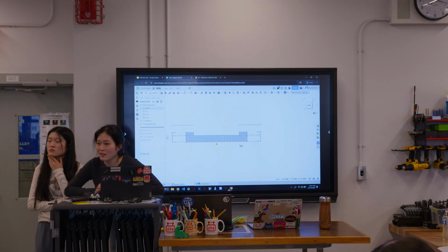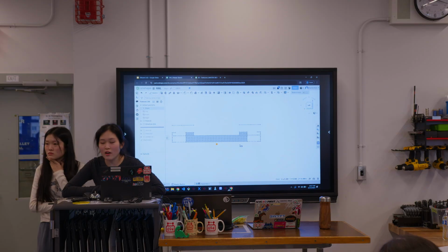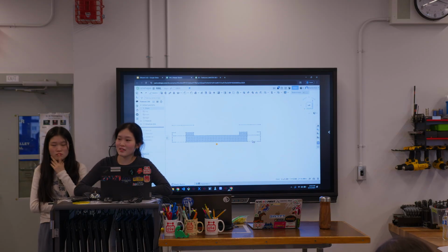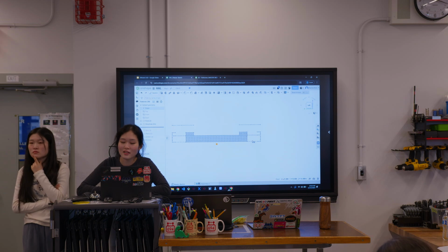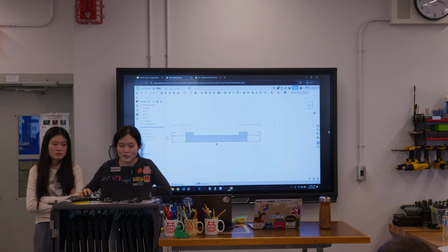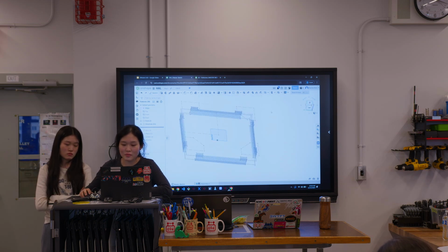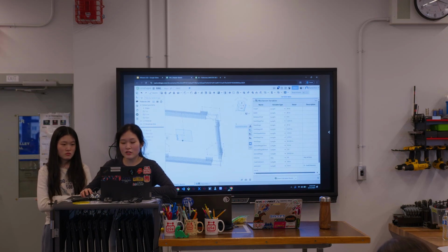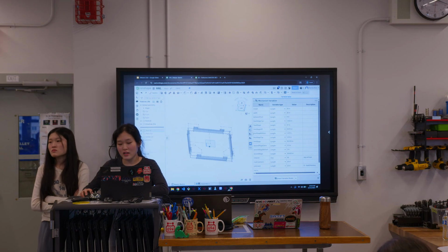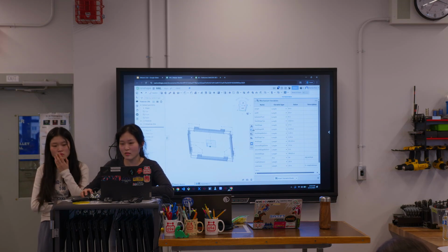Yeah, I was just going to ask: is there an advantage to sketching out the drivetrain rather than building your master sketch off of a 3D assembled drivetrain? Yeah, that's the one thing that stays stagnant, right? You're going to design all. Oh yeah, that's true. The reason why we sketch instead of using assemblies is because let's say you need to change your robot dimensions, and this was something that actually happened during the season. We weren't sure if we wanted a rectangular robot or a robot that leans more towards a square.